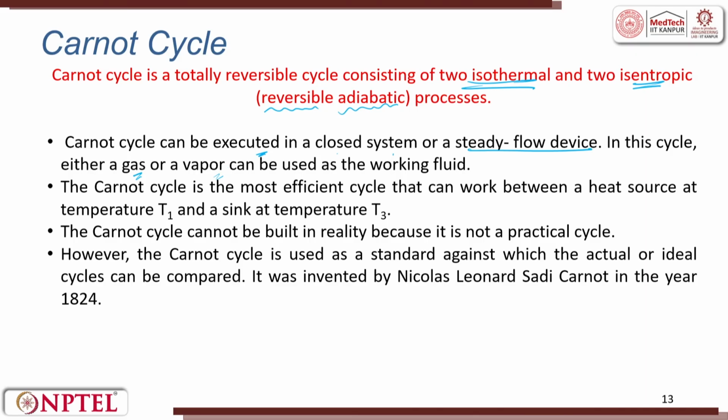The Carnot cycle is the most efficient cycle that can work between the heat source T1 and the sink T3. The most efficient engine is the Carnot engine. The Carnot cycle cannot be built in reality because it is not a practical cycle. However, the Carnot cycle is used as a standard against which the actual and ideal cycles are compared.